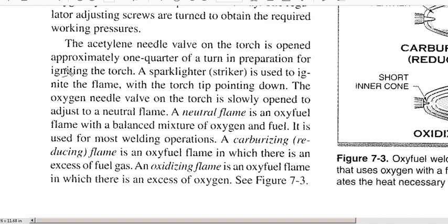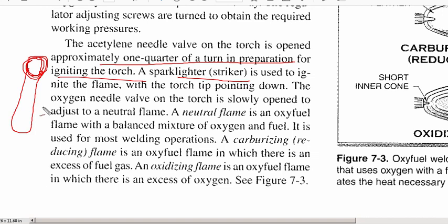Needle valve in the torch is open approximately 1/4 of a turn, preparation for igniting the torch. Your striker, that handy little thing that looks kind of like this. We have an old school one there. My grandfather was a pipe welder, and we had a lot of old equipment from his days on it. So anyway, the striker in there, and you get your flame tip created.